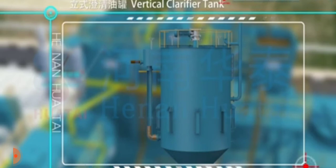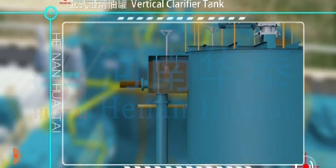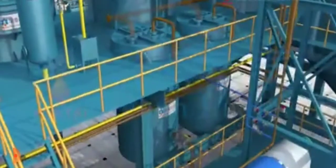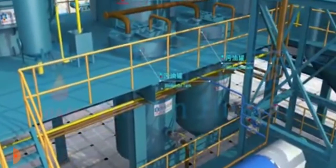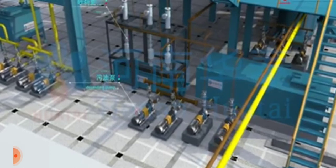Dirty oil in the vertical clarification tank enters the dirty oil skimmer from the bottom. Then it enters the dirty oil tank. Convey to the desanding cyclone with the desanding pump.